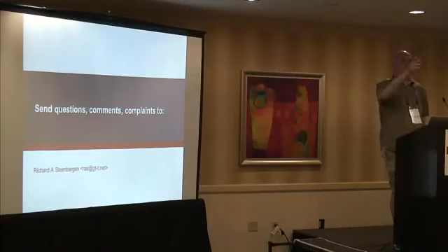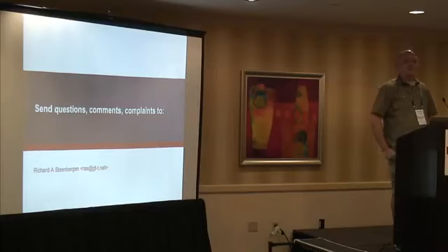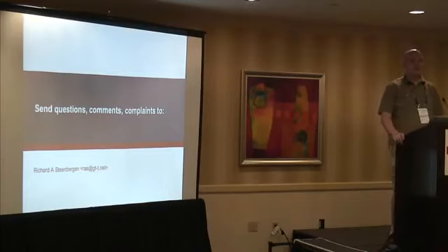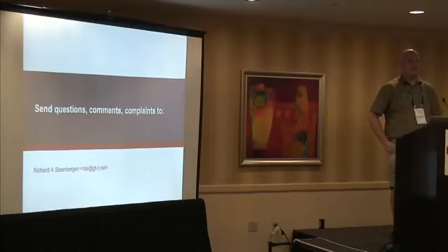Can you comment on ALS? Do you like it as a feature? ALS, automatic laser shutdown? Not something I'm super familiar with, but there's a lot of safety techniques out there, and that's one for if you've got a fiber cut. You don't want an extremely powerful amplified signal going out, and so systems will detect a cut and turn off the laser. It's a good safety feature, but it's not something that you'll typically encounter outside of a very commercial, long haul type system. You're not going to see this on any routers or anything like that.